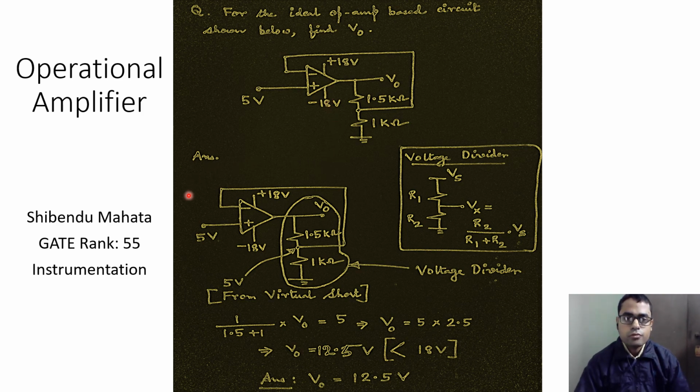Okay, so with the circuit shown here, the first objective is to note that if the voltage at the non-inverting input terminal is plus 5 volt, then the voltage at the inverting input terminal should also be plus 5 volt. And then because this is shorted all the way to this node, therefore the voltage at this node is equal to plus 5 volt.